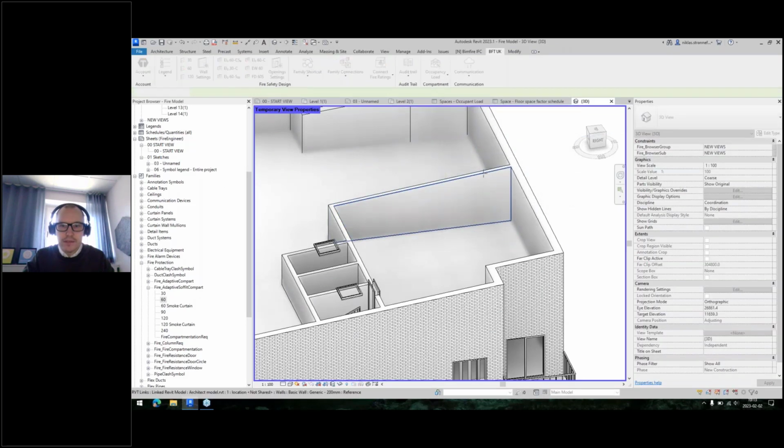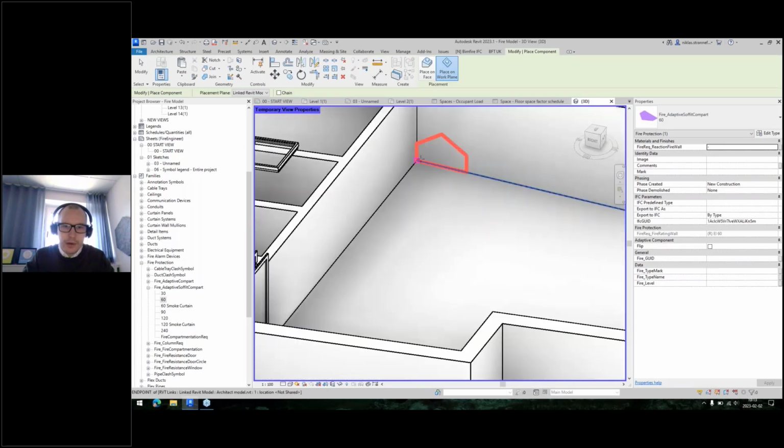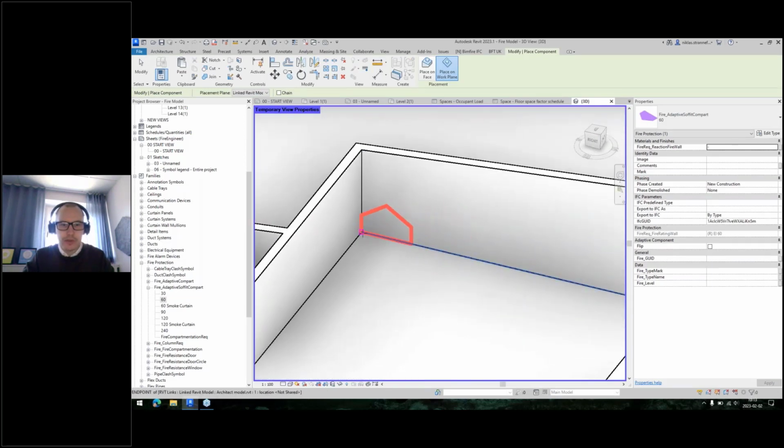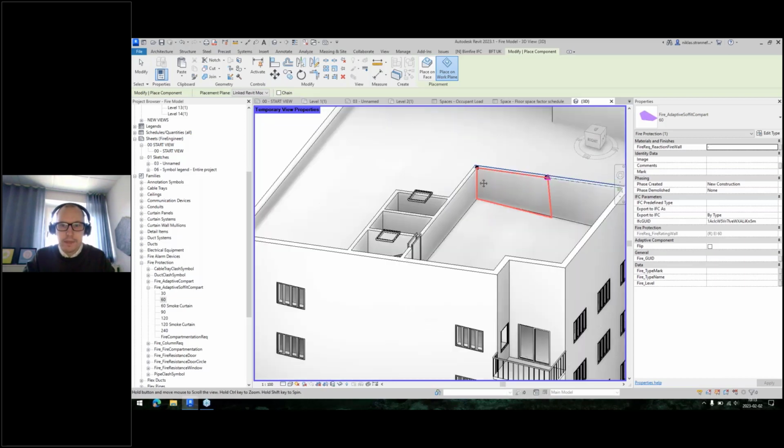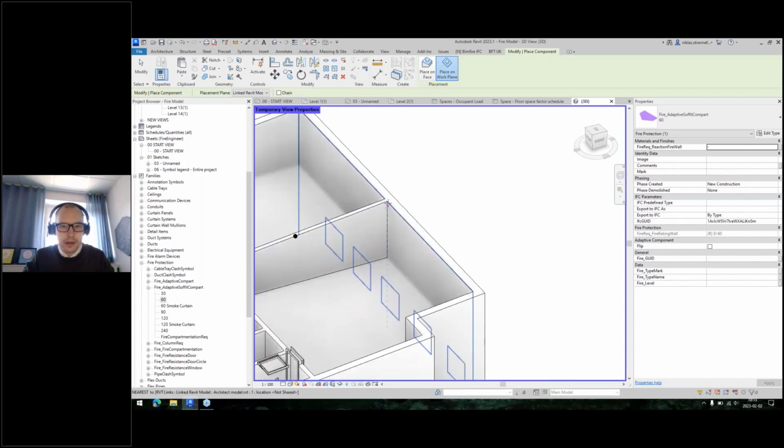And now we can select the surface of this wall because this is the one that we want to draw on. Or we can change to any other. We just select the wall we want to draw on. You select that one. And once it's selected, we can now easily, just in 3D, select 5 points. 1, 2, and I'm gonna pick the middle of the wall, but if it's a different height, or in this case 2 slopes on the wall, we can use that, of course, but this is 1, so I'm gonna just select the middle of it, and I'm gonna add the 2 last points here, and I'm gonna select you and the very bottom down here.